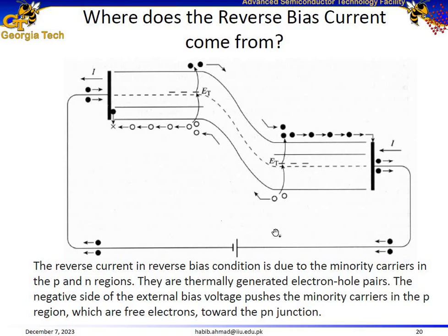We know that under reverse bias, we apply positive potential to the n-type layer and negative potential to the p-type layer. Applying positive potential to the n-type layer means that the energy levels on the inside would be dragged down. We have this big barrier for majority carriers to flow across the junction.